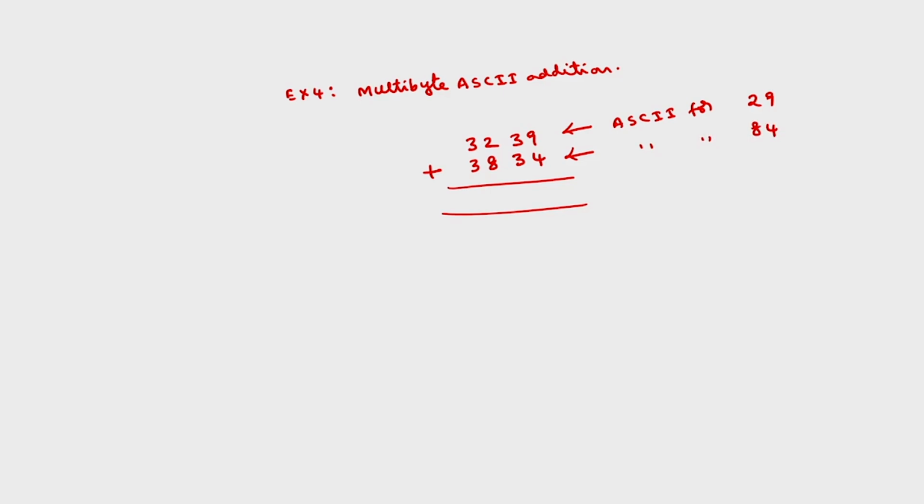As I already discussed while discussing the ASCII instructions, 0 is nothing but 30H. If I press the 0 key on an ASCII keyboard, internally 30H will be generated. You simply add 30 to that key. 1 means 31, 2 means 32, and so on up to 9 means 39.